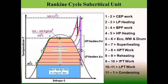But the purpose of circulation is very clear. It actually intends to continuously wet the surface of the water wall tubes and necessitate the heat absorption at a rate which is not detrimental for the tube surfaces.